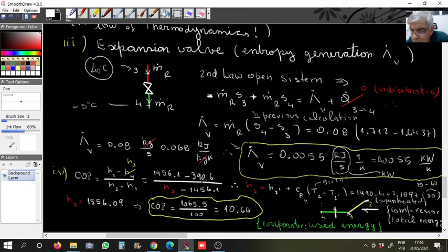Professor, I want to transfer this to Kelvin. Doesn't matter, because you add 273 here and subtract 273 over there. So when you have a subtraction, you just use degrees centigrade, no problem. It will be 30 over here, because T2 is given as 70, and T2 prime is 40. In this case, it's 40 degrees, the hot temperature.